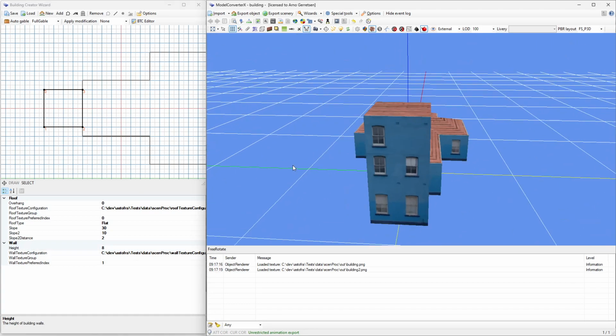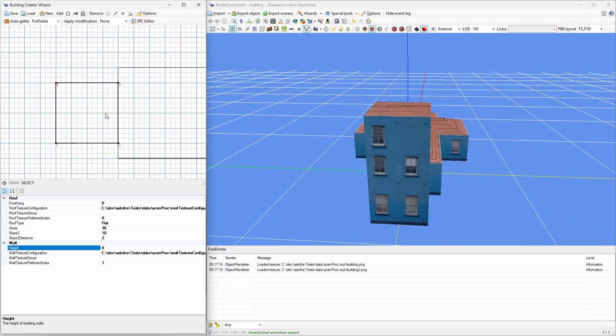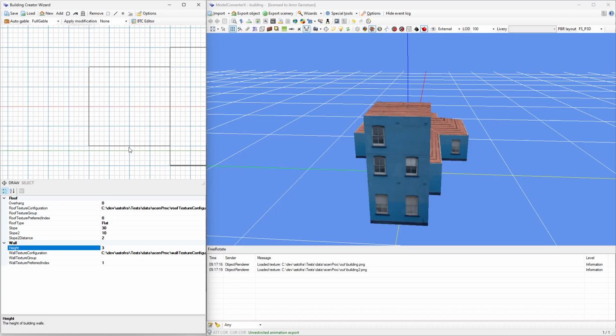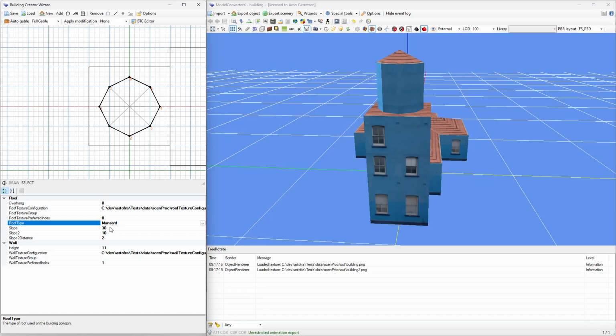So we have the back of the church and a tower, that's maybe a bit overkill. And in that tower I think we can get away with, let me see how I'm going to render that. I do this one, this one, this one. I made the tower 8 meters, so let's say I do this one 11 meters. And this one will get a mansard roof where we get, let's say 20 and 60 degrees. Lower this distance a bit more.